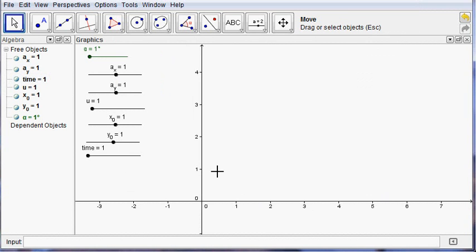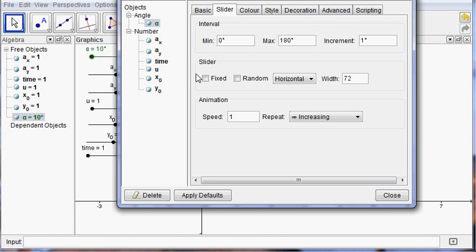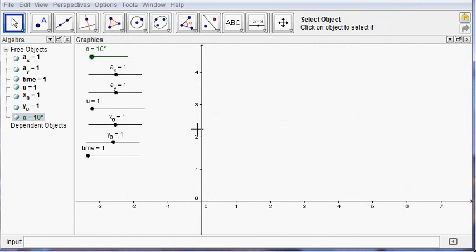Now here are some typical values which you might use for a projectile motion simulation. Set these to whatever you want. Try that again. I'll actually double click this here. Okay, so typically in a high school question that will be 0, horizontal component of acceleration. Press enter to accept that. This one would normally be gravity, so it'll be something like -9.81, or it could be -9.8 or -10, depending on the accuracy that your question requires. Time, I'll just leave it 1 for now.